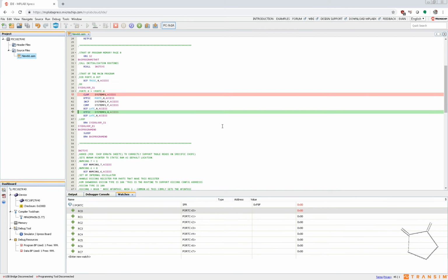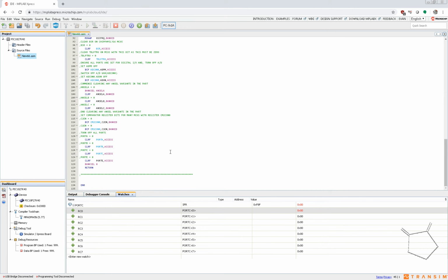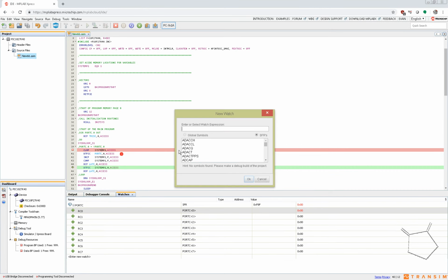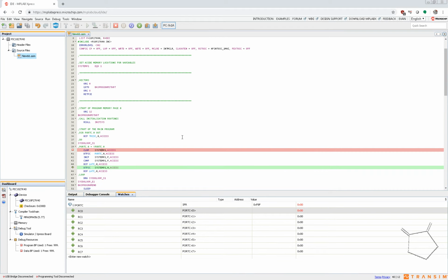We have two ways of using this tool. This is a really simple way of understanding what the code is doing. If you want to see it run through the registers and all the config, etc., you can use this. This works quite well. You've got all your SFRs sitting there. You're not going to see the config necessarily, but trust us on that. It's quite a good way to see what's going on and learn what's happening with the code. You've got access to the data sheets here. You can see what we're doing. It really does work well.